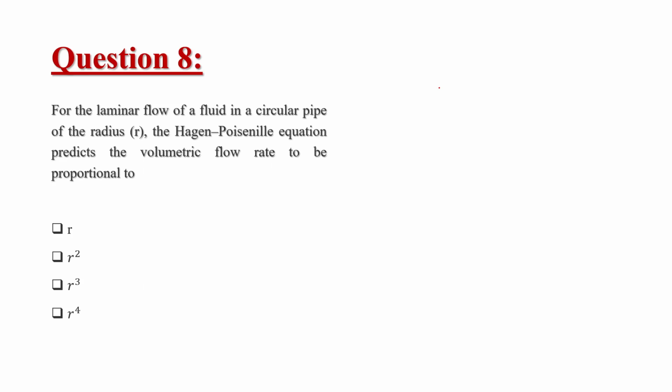Okay, let's see. Here it is given that there is a balance of forces acting on the respective faces of the assumed small volume dx dy of unit width, and the velocity distribution is given as this, which is a parabolic equation. To obtain the maximum, y can be replaced as h by 2. So we know how to obtain the maximum velocity, and at what y we will be getting it. To get that, we have to set dou u by dou y equal to 0, that is du by dy will be 0.